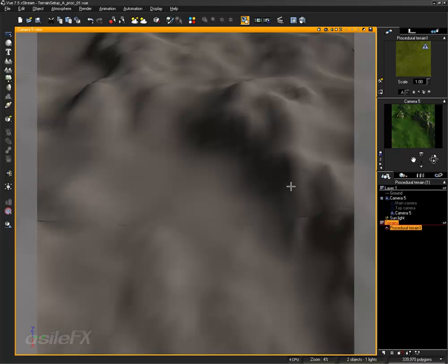One was taking the bump, or basically the fractal that I used to generate the terrain, to overlay and connect to the bump channel, which would in turn create a vast amount of detail on the bump channel on a standard terrain created from a procedural. But that also would have the same problem with animation, and also could take longer to render because it is calculating that bump.